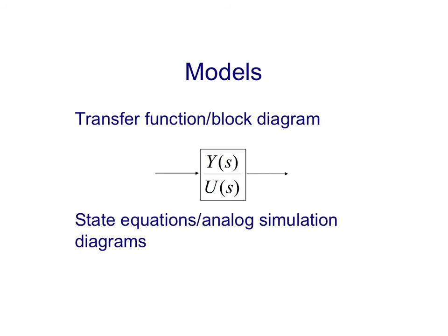Besides the differential equation, we can describe a model using a transfer function or block diagram. And the transfer function is the relationship between the Laplace transform of the output with respect to the Laplace transform of the input. Another way to describe them are state equations, and we use analog simulation diagrams, which we will see later on in the course.